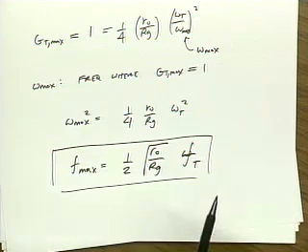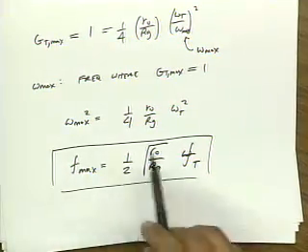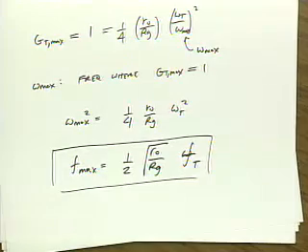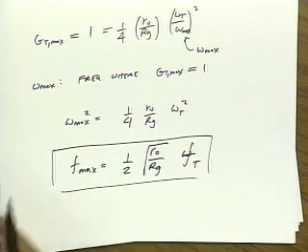Remember a couple of lectures back we said, why can't you arbitrarily tune out parasitics at a terahertz or 10 terahertz or a billion terahertz for that matter? That's because you won't get power gain out of your device. Actually, it turns out it's really hard to design inductors and capacitors at those frequencies, but in theory you could. You just wouldn't get power gain out of your device. Your device would be useless. It would just be a passive device, providing no power gain.